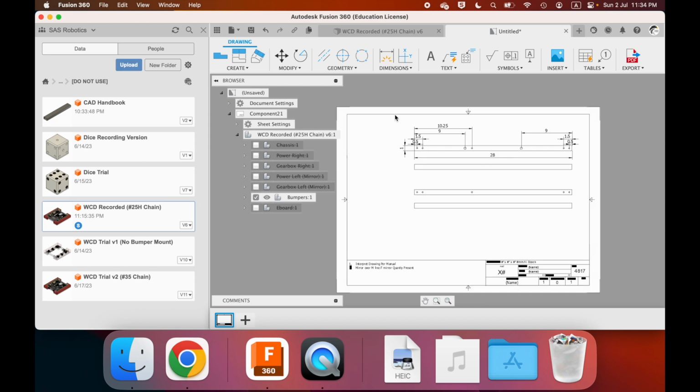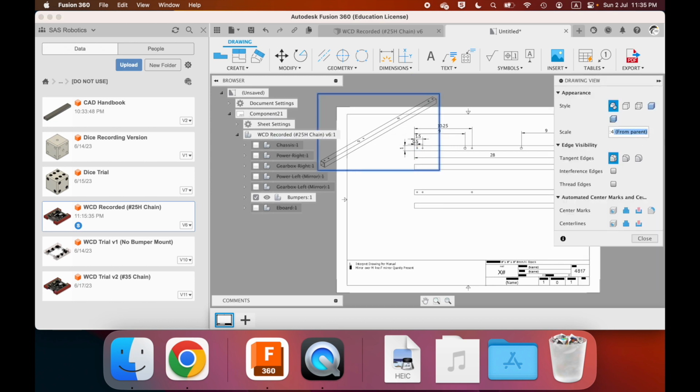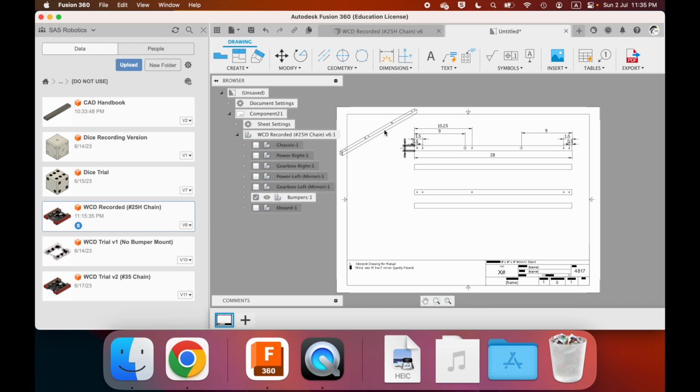Okay. So the isometric view that goes in the corner. You need to project this isometric view from the second view, not the first one. Okay, you drag it over to the left like that, and then it does the right isometric view. And then we always resize this. So I'm going to go edit view, and I'm going to change this to, let's try the 1 to 10. Yeah, that's like it. Maybe 1 to 7. It's a bit big.